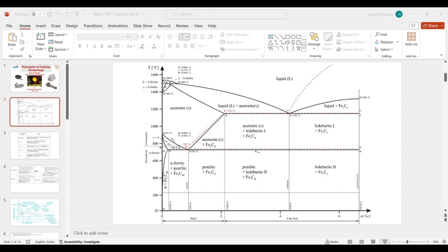What we will do is add some austenitic stabilizers to the steel. Austenite basically has an FCC crystal structure. So we will add some elements having an FCC crystal structure to your steel system to make this alloy.